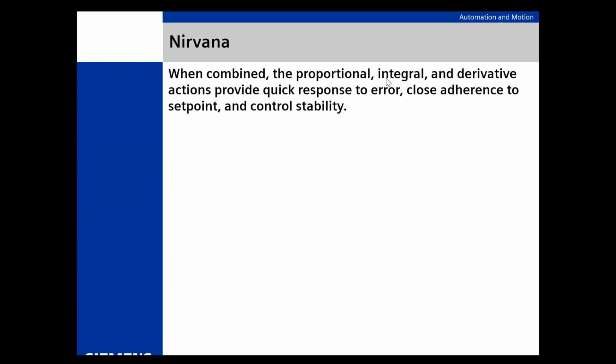We do the best we can to avoid chasing the PV within an established range. Deadband and output dampening helps. Absolutely. Well, see, whoever said that obviously has some experience. Yes. What operations and management, people in white shirts, want is that come to set point and be a flat line forever. Well, guess what? Ain't happening.